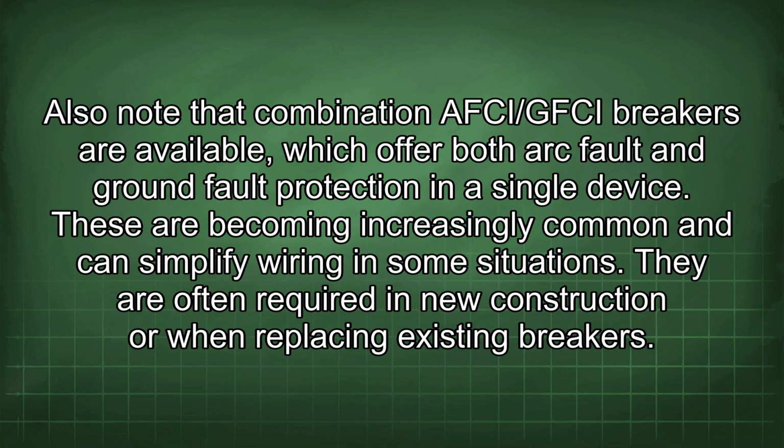Also note that combination AFCI/GFCI breakers are available, which offer both arc fault and ground fault protection in a single device. These are becoming increasingly common and can simplify wiring in some situations. They are often required in new construction or when replacing existing breakers.